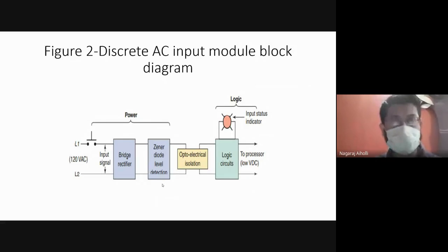Initially, when you apply the reverse voltage, microamperes or nanoamperes, very little current flows. When you reach the voltage called the Zener voltage or breakdown voltage, the current flowing in the Zener diode is large. A suitable amount of current flows at a particular voltage level. So this property of the Zener diode is used in finding the voltage level of the bridge rectifier.